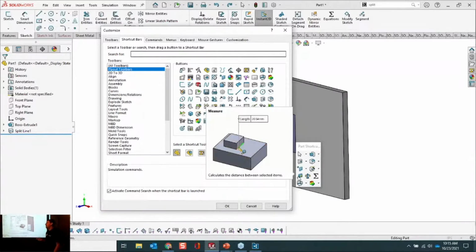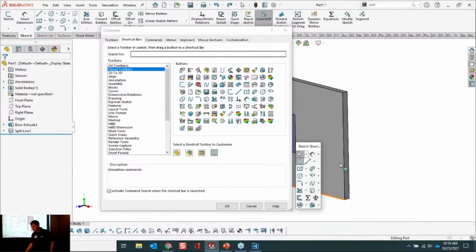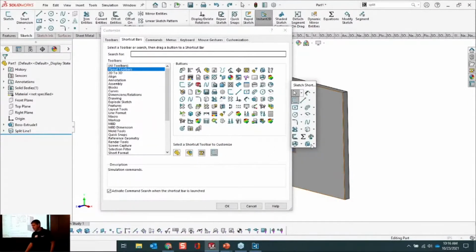It really just depends on what I'm doing that day, but my S key changes maybe once a week. I do much more sheet metal and features, so I just prefer to have those toolbars on there. The thing that makes you really, really fast, in my opinion, is putting your flyout toolbar for features on the S key, because then you don't even have to touch the ribbon. And it's sensitive.